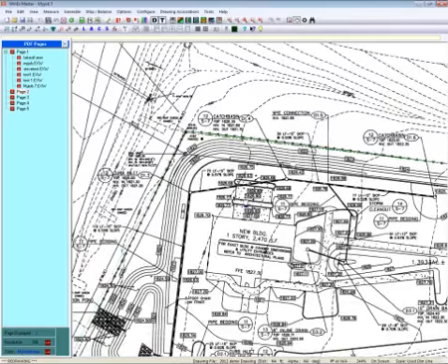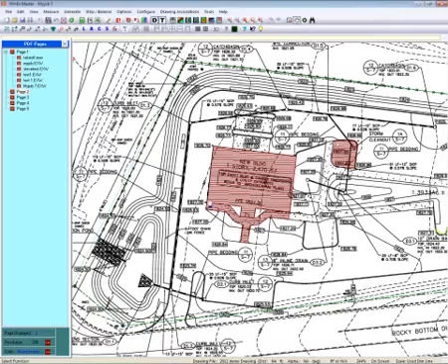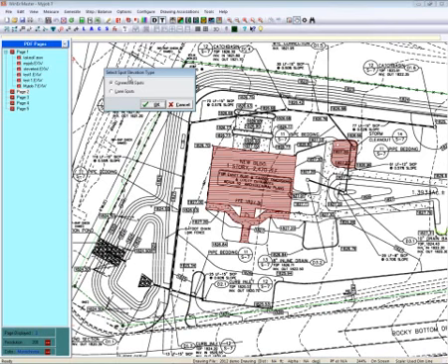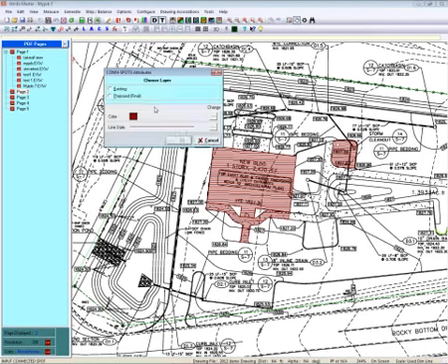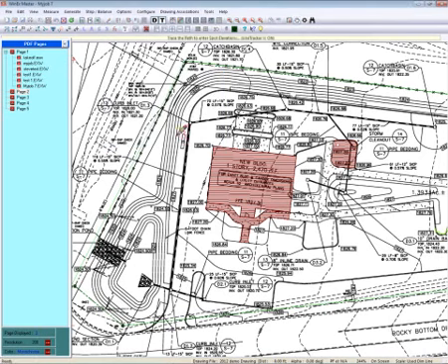And I could have made that a different color. But now let's say this walkway slopes for drainage. And this is the higher portion of it. And maybe it slopes down here into the parking lot for some drainage. Come over to your spot elevations. And for this particular routine, I use our connected spots. This is a very simple routine to put in. Click OK. And we'll say these are proposed. And I'll automatically change that to yellow. I've already got that set up for spot elevations.